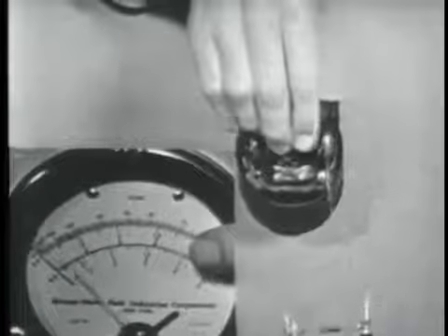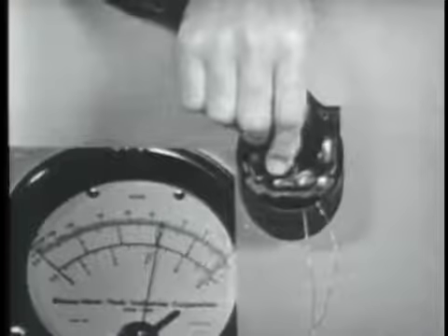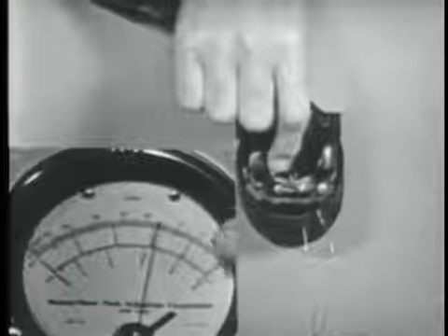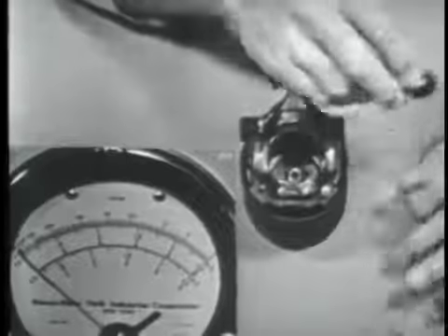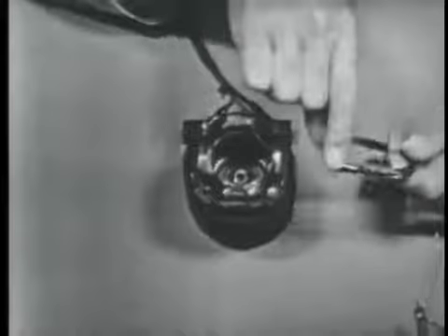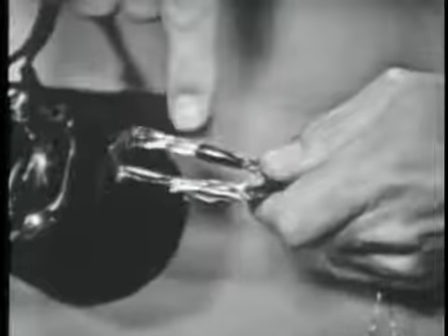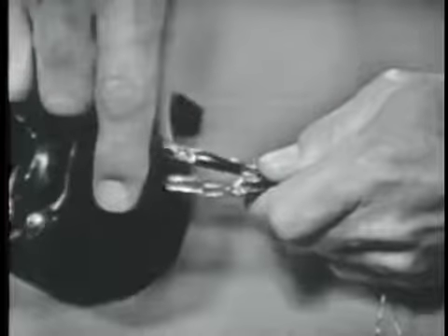And you can see as I take the loop out, it goes away, put the loop back in. I've got to get the loop all the way down in there. There you go. Now we have the rotating magnetic field inducing a voltage into the loop, which we're reading on the PSM6. Now the important thing to realize here is that once we get current flowing in this loop, we have a magnetic field established about the loop. Now this means that we'll exhibit a north pole on one side and a south pole on the other. Or in other words, we have magnetized the loop. Made it an electromagnet, right?